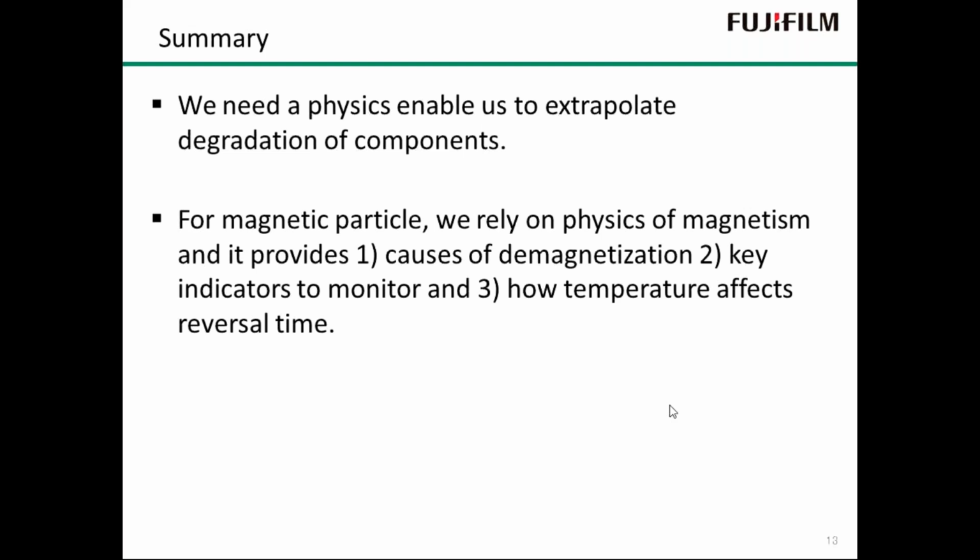When we started LTO back in the late 1990s, there were tests that we defined, and they're probably still in the spec. I don't know, actually. I haven't looked forever. Like there was a mag coat pull-off test, because at some point we had magnetic coats delaminating from tape. Somebody defined a test where they glued a test specimen of a certain size on a certain piece of media, and if you pulled it tangentially, you should get X force. That was an example of a trial to accelerate runnability evaluations.